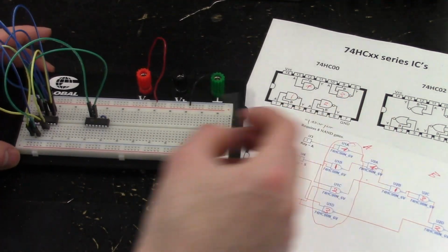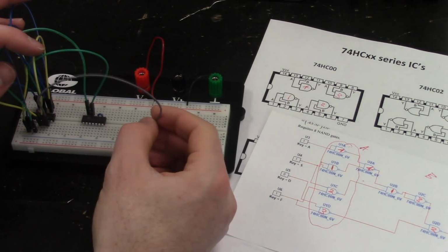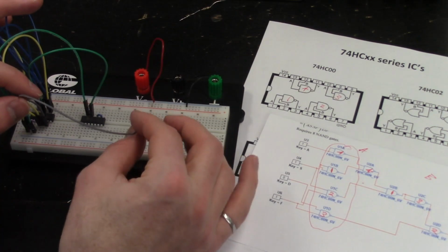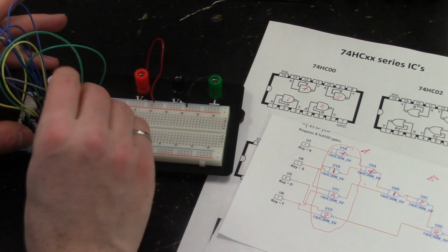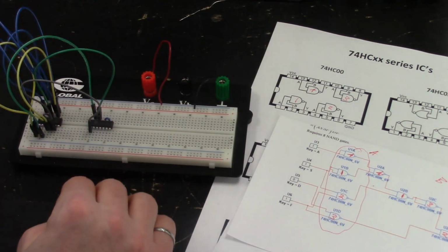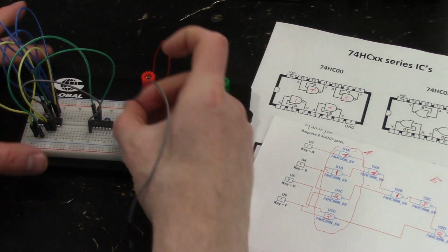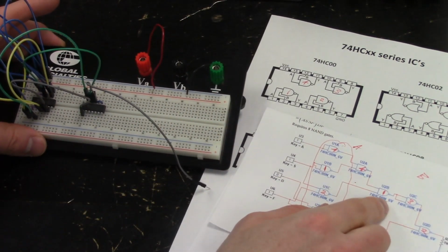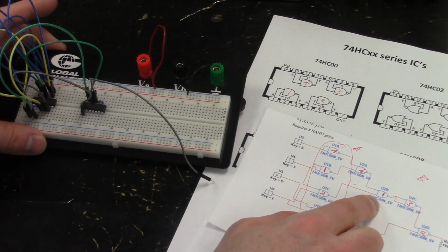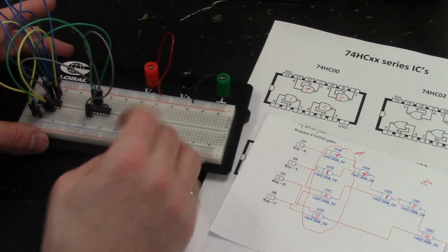And 2 was this one down here. The output is on pin number 6. And we'll put that over to 1 on the second chip. So that's this one there on that input. And then the other one going into this gate 1 on the second chip is 4. So we'll take the output of 4, which is up there on pin 11, and we'll bring that over to pin number 2.